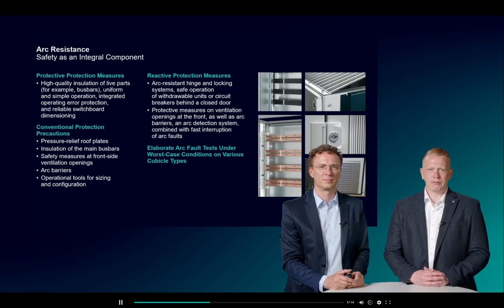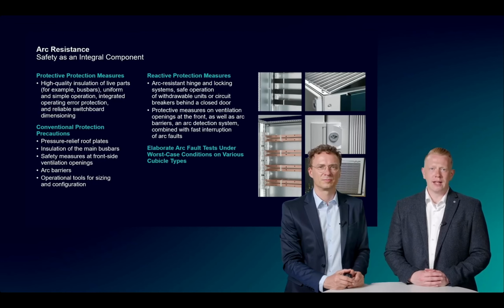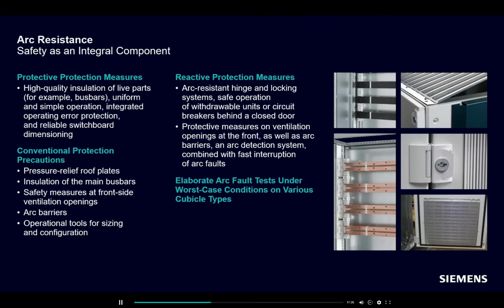The important thing here is that we have a meshed structure. That means if we have a short circuit somewhere on one line, the current comes from different sides, from different directions into our line. And that is an important fact to define the protection.